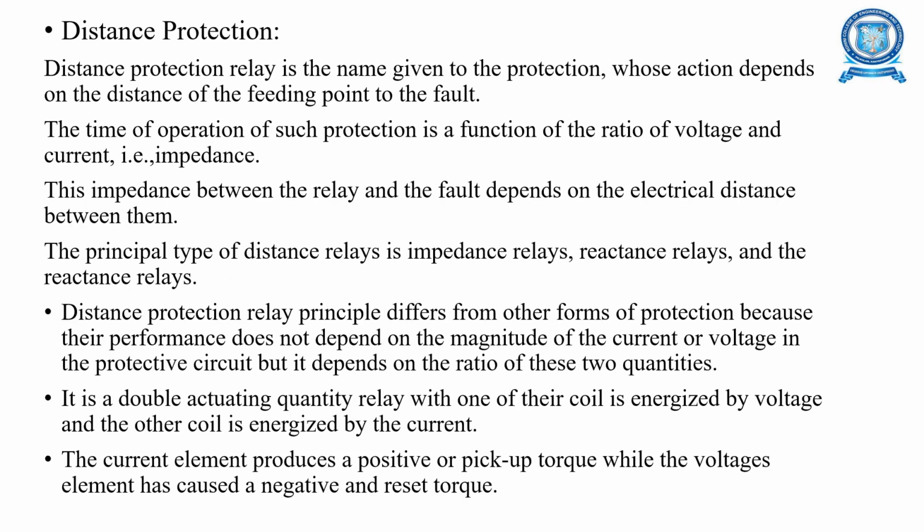Next is the distance protection. A distance protection relay is the name given to protection whose action depends on the distance of the feeding point to the fault. That is, the impedance between the relay and the fault depends on the electrical distance between them. The principal types of distance relay are the impedance relay, the reactance relay, and